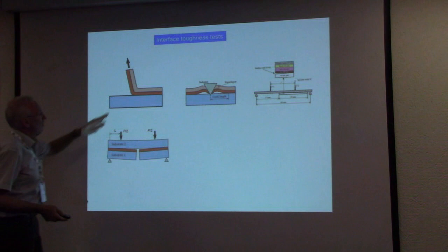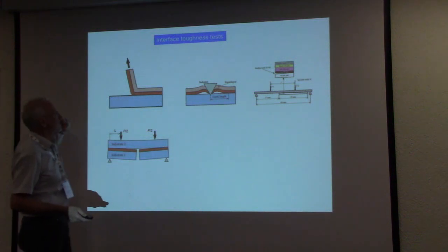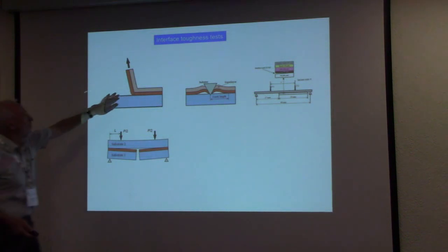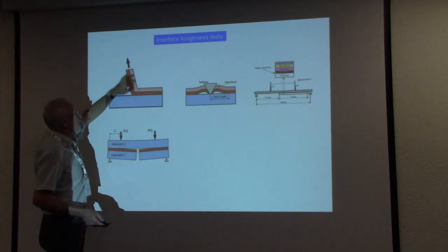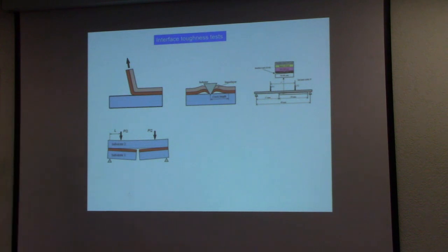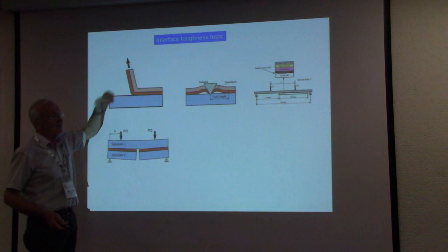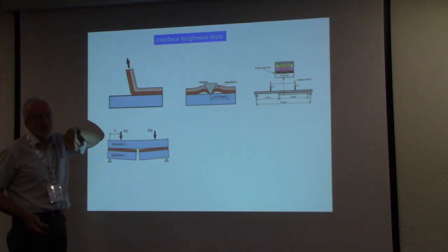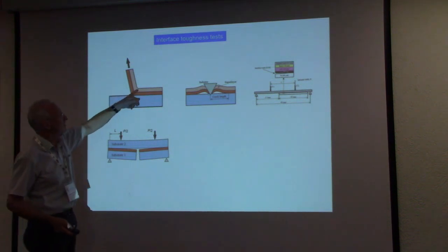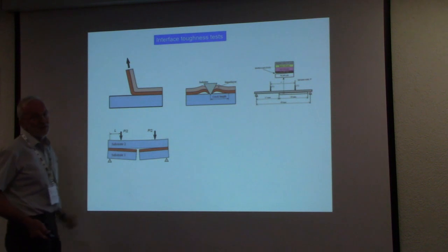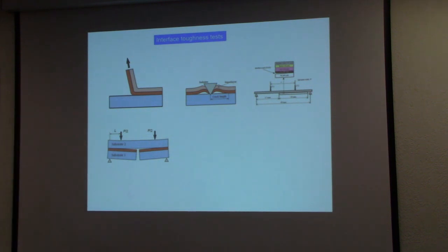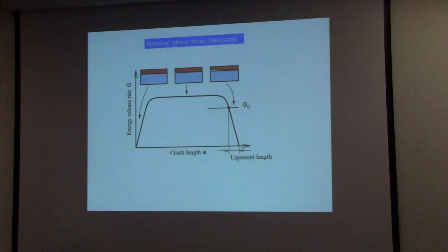But what you have to do is, if this is a compliant film, then it is not really a problem. But if you touch a quite strong material and plasticity is involved, then plasticity is also constrained. In addition, there is a different constraint effect if you have a free surface and a constraint only on one side or a constraint on both sides.